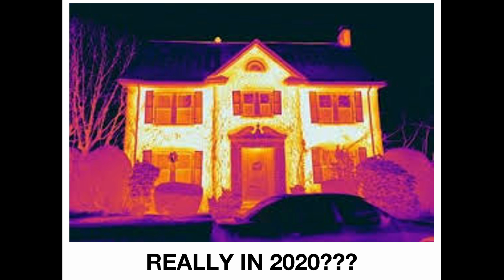Now, if we are saying that we can have an air change rate of 10, that means that that building can leak up to 10 times that. So 240 cubic meters times 10 is 2,400 cubic meters that building can leak every hour, and it will still pass building regulations. Now, you have to ask yourself, is that acceptable in 2020? I would argue that absolutely it is not.